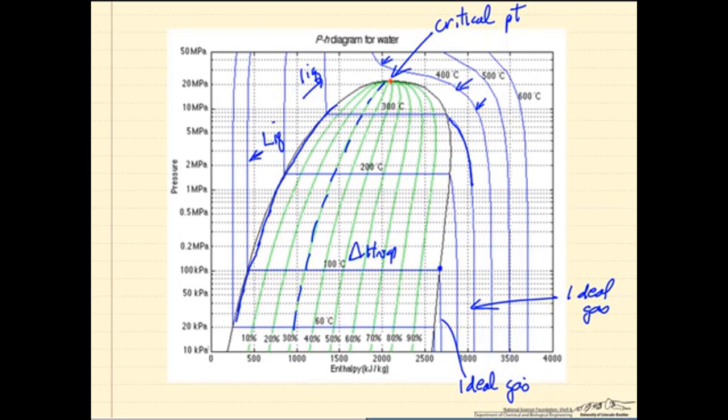Other thing we want to look at is this saturated line. Notice as I increase the pressure, the enthalpy increases for a liquid at saturation conditions because the temperature is also increasing. To stay on the saturated line, pressure and temperature both increase. Stay on the saturated line at a higher temperature, I have a higher saturation pressure, and therefore the enthalpy increases.